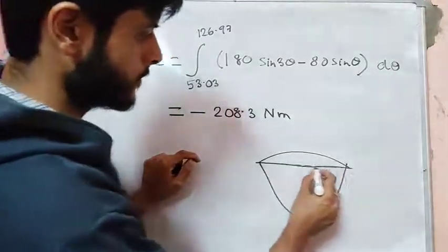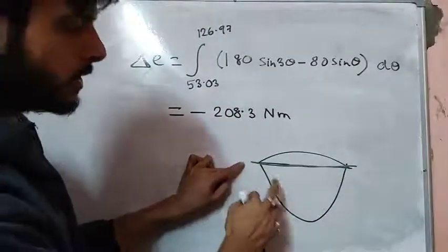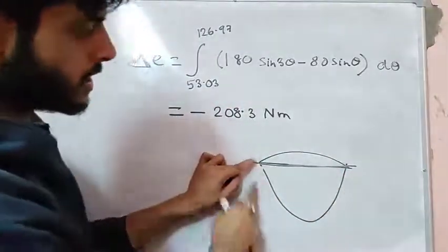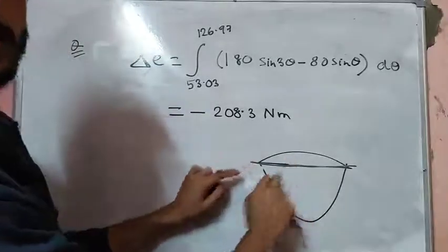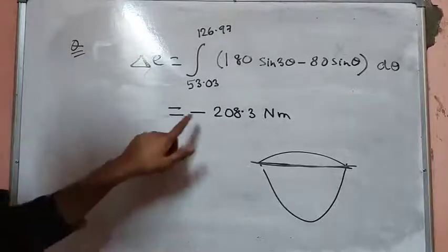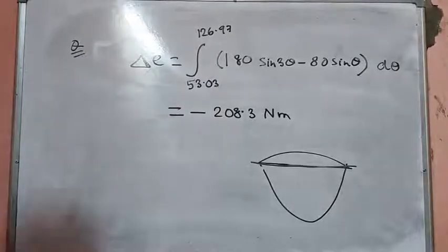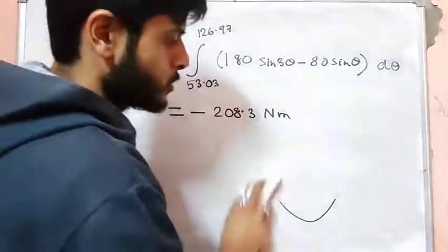This was the mean line, right? 800 was the mean line. So this curve was more. The area under this curve was more as compared to this, right? So the minus was evident. Okay. So this minus implies that the flywheel has given some energy to the system.